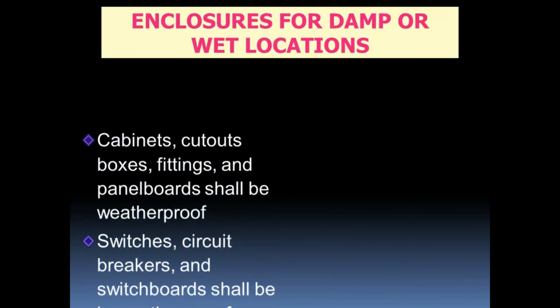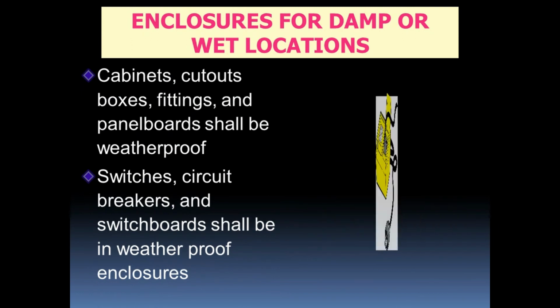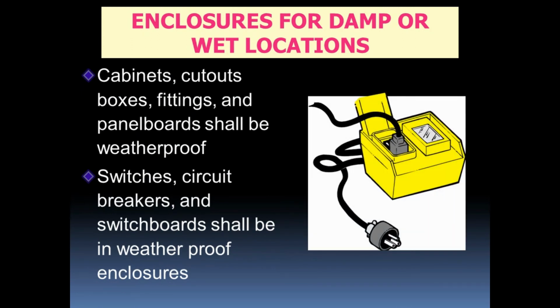Closures for damp or wet locations. Cabinets, outlet boxes, fittings, and panelboards shall be weatherproof. Switches, circuit breakers, and switchboards shall be in weatherproof enclosures.